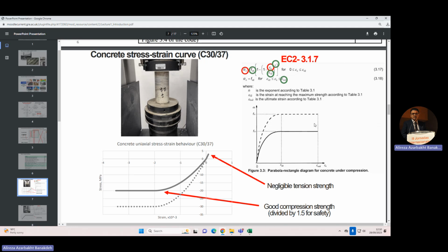Yeah, but it's easy. It does not say EC2, so that's not. Yeah, that's what I was saying. For which point? You should assume epsilon and calculate sigma, not vice versa. You should assume this one, but calculate this one. Any number from this. Okay, you said I will get 2.2 here. You should get this number. But it's better to get something between 0 and minus 0.5 divided by 100. So we need to choose from here to here.